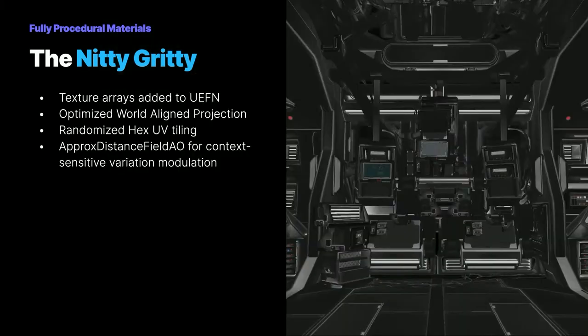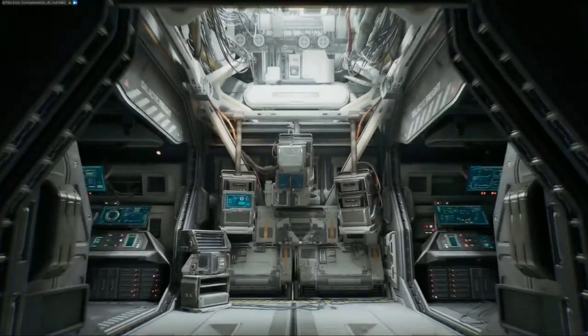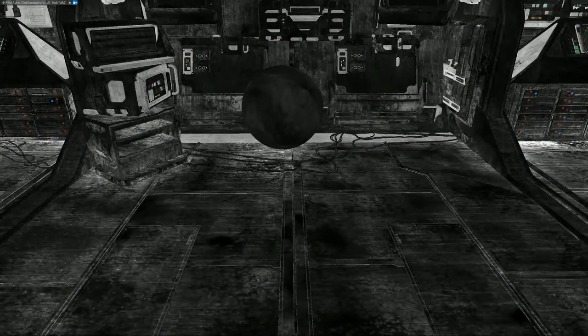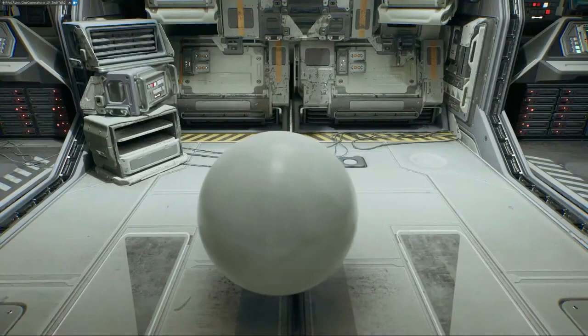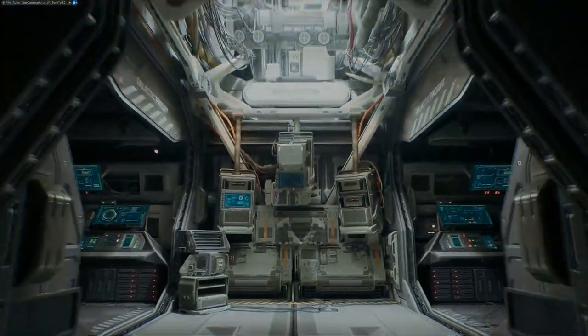Our mesh-based ambient occlusion data is super important, but it really only considers the atomic asset, not the context in which the asset is used next to other objects in your scene. So to further enhance the feeling of cohesion of our heavily kit-bashed scene, we made sure to also ingest distance field-derived ambient occlusion. The incredible benefit of using DFAO is that it reacts to our set dressing. You can see here that grime and dirt accumulations update when our set dressing changes. Using it on top of our mesh-based data massively helped in really making everything in the level feel connected.